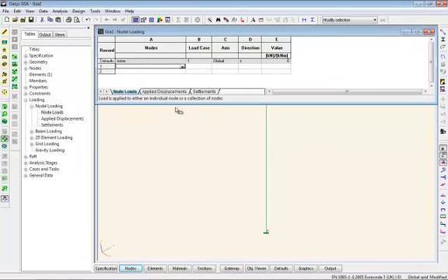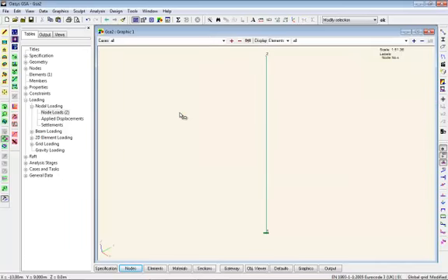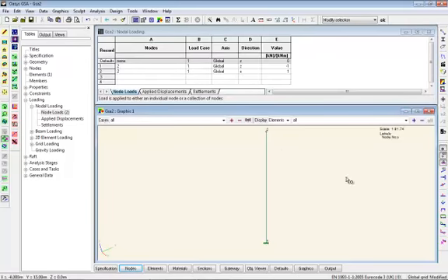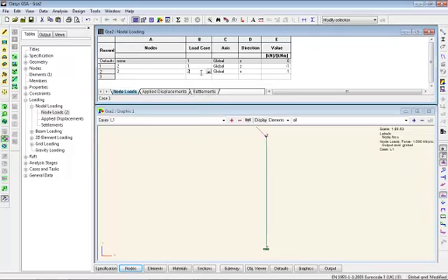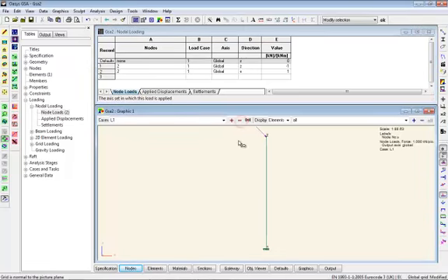Let me just add in some loads. So -1 vertically, so axial load, and a horizontal load, which will combine together to show us. GSA takes these two vectors because they're in the same load case, but if I make that load case 2, you see we've got vertical load and horizontal load, and they vector together to make the one.